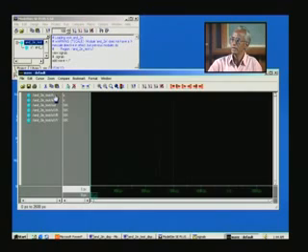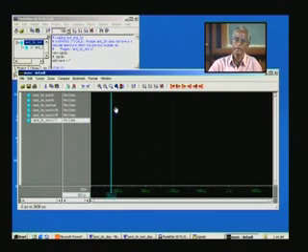And if the waveforms are displayed in this fashion, it may be too crowded for you. Fortunately you have one way out of this, and that is what is called format. Just click on the format. Now nothing happens because all are de-energized. So we should first make a run, then we'll see format.